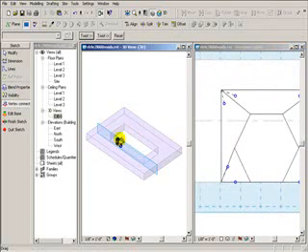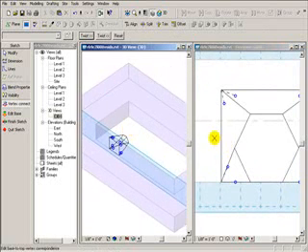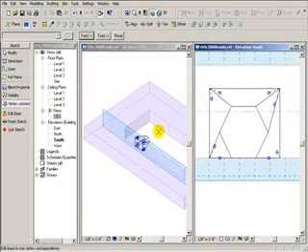I can zoom over here, you can see a little better. If you notice, my void blend is actually going in the wrong direction, and I'm not concerned about that because I am going to align this exterior portion that's in my interior shell to my mid reference plane, work plane. So I'm going to finish the sketch.